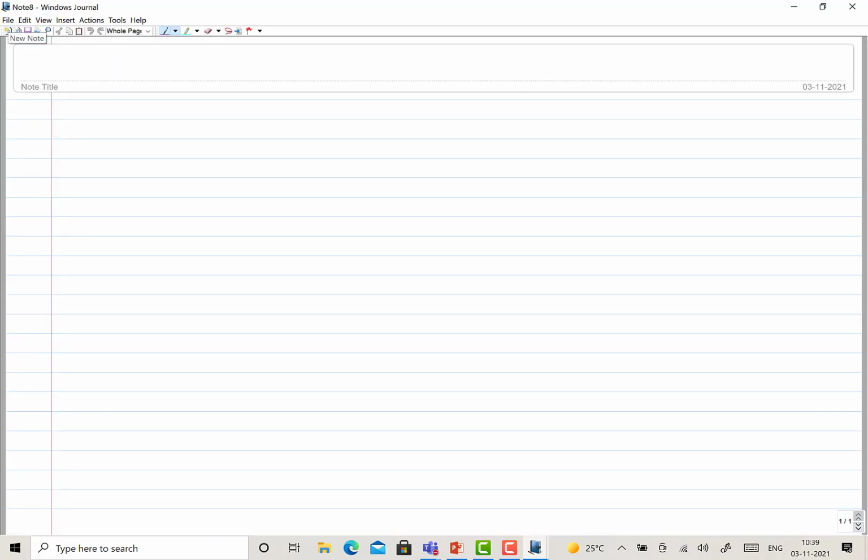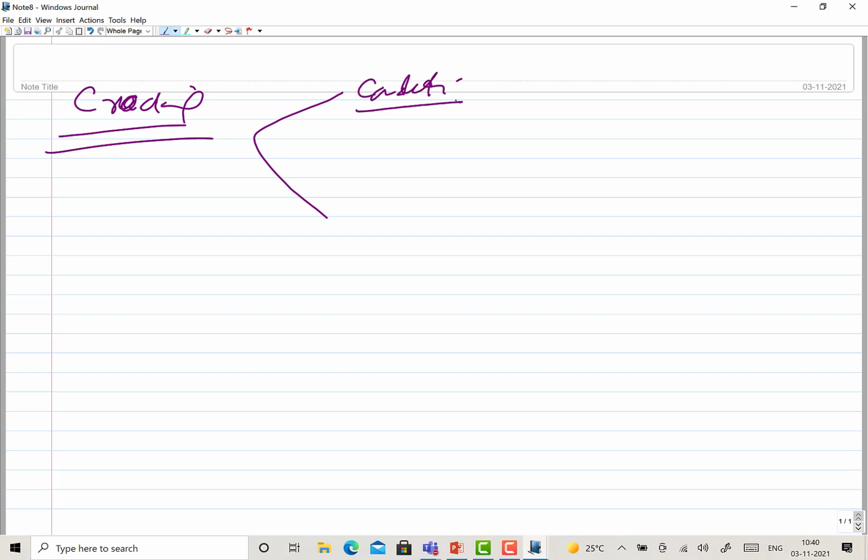So whatever your arc welding process, use proper shielding through the proper flow rate of the gases, or use proper flux so that the impurities form slag and they are removed. Okay, so this was the second one, and the third one, which is very common, is cracking. Now there are multiple types of cracking. Let us understand this based on the conditions in which the cracks are developed, and the location where these develop. Okay, these are the two broad classifications.